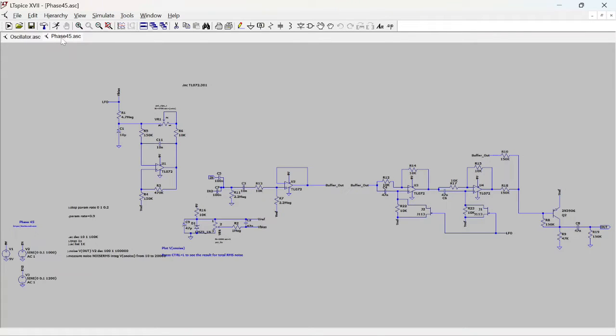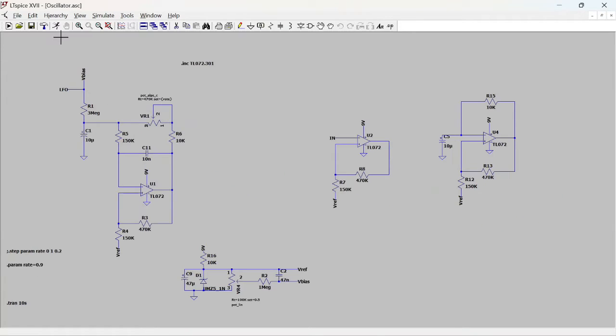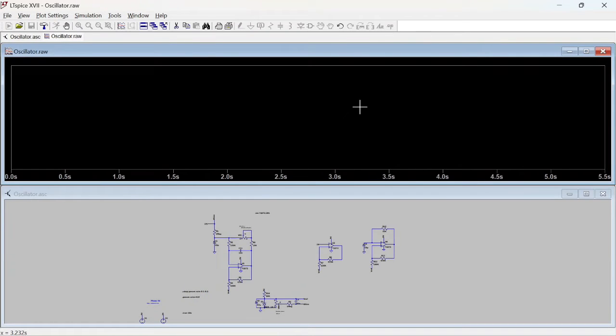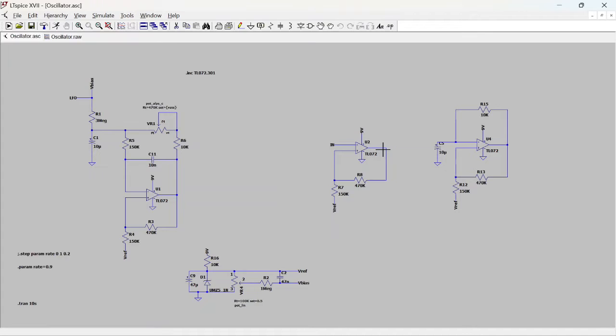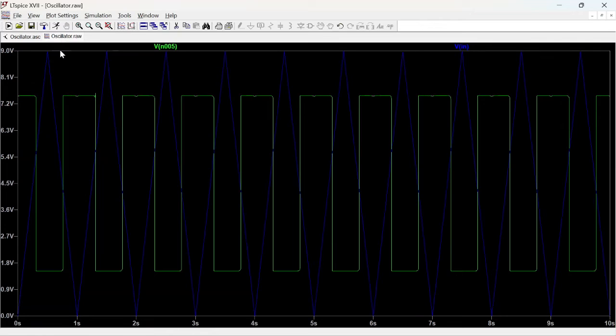But I'm just going to focus on this part here real quick. So how does this Schmidt trigger work? If you have an input, let me run this actually. So let's see. Let's sample output and input. And for input, I just have a sawtooth signal.